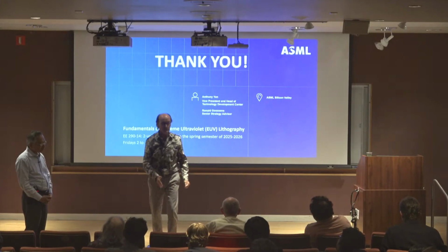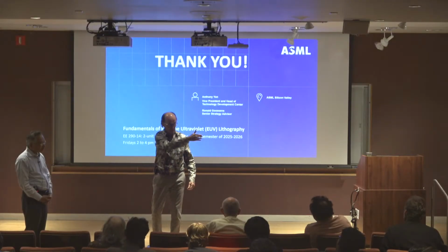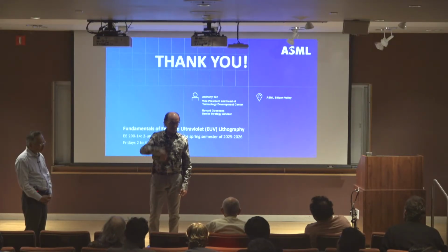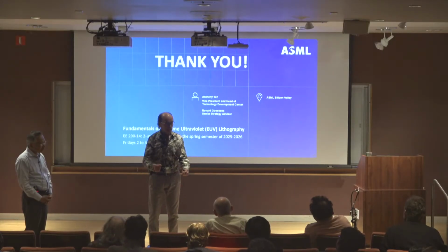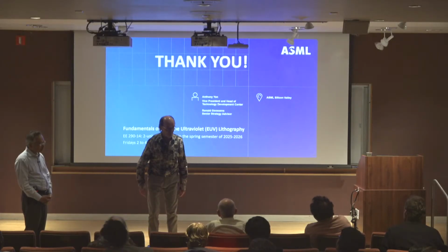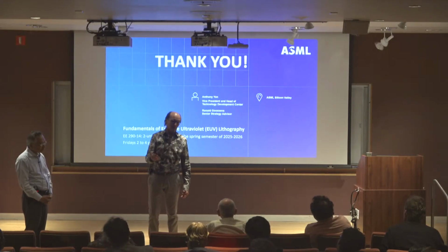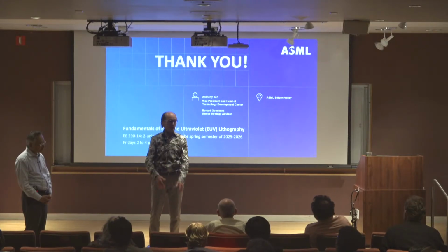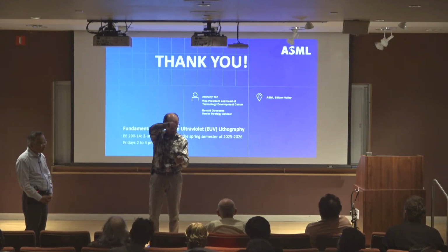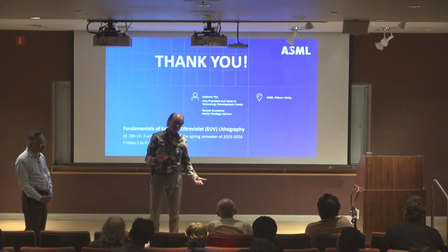I would now have great contrast in this direction and zero contrast in the other direction. So the only thing that I can now do is print lines that are infinitely long. Not a single designer is interested in that. So now what you could do as well, but if I have those very long lines, I will use a second exposure to cut them, but that's expensive.